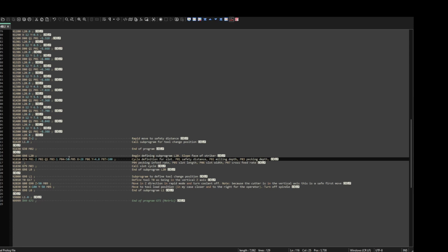So it doesn't have to drill down that 1 millimeter for each peck with the ball nose cutter. Probably could, but it's probably better practice not to. So I've just made it go 2 millimeters beyond the part each end.